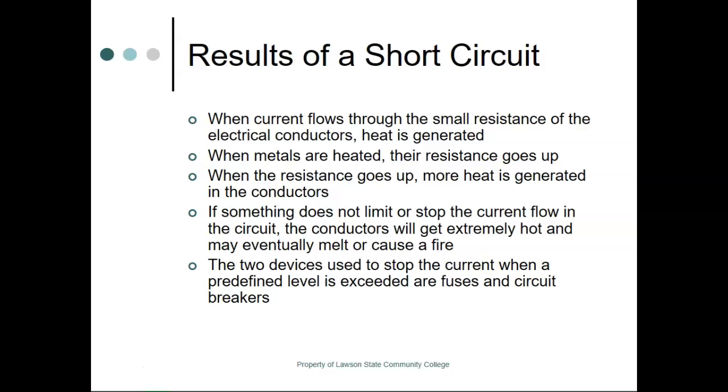So when metals are heated, the resistance goes up, and it becomes a feedback loop. The more resistance it has, the more current is being shoved through, the more it's going to heat up, and it just keeps going through this vicious cycle. And one of two things will happen. Yes, you could very well get a true arc over and cause a lot of problems. Probably two worst case scenarios.